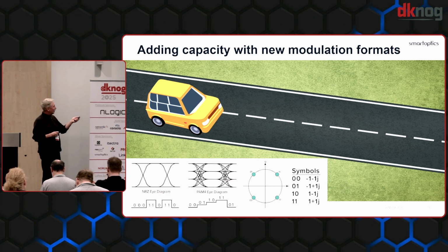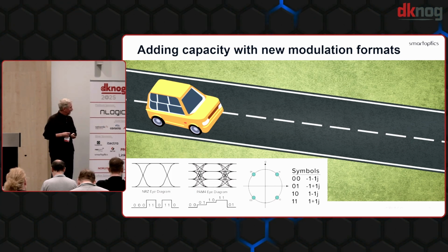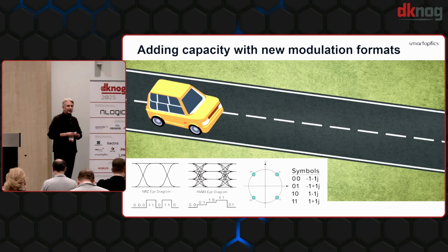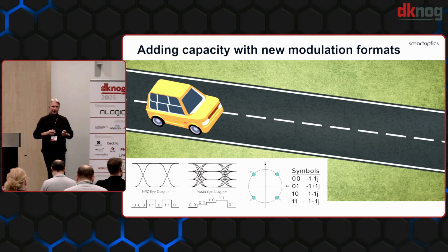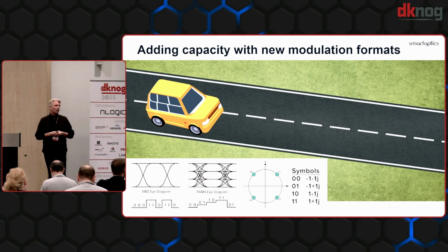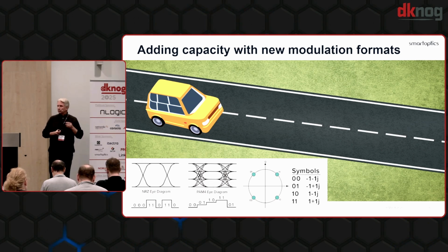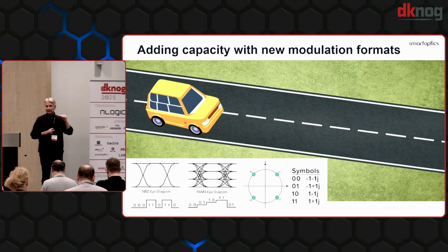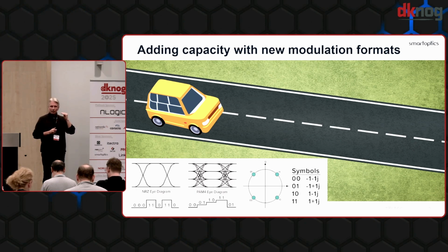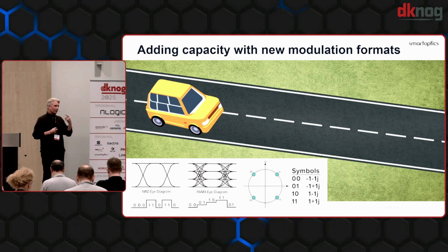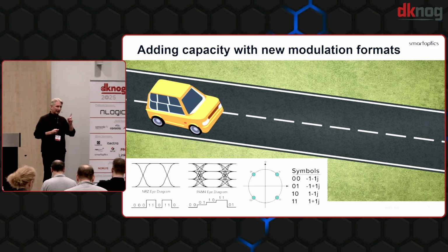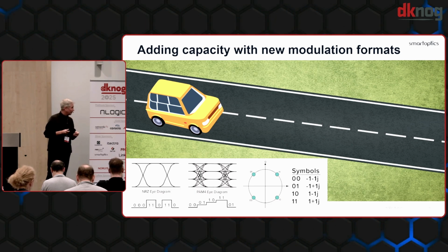If we look at the modulation format, NRZ modulation is a modulation where you have 1 bit representation per clock cycle. Normally people talk about turning the laser off and on. That's not really how you do it. You have different light intensity levels that represent 1 and 0. So the 2 states that you can have are 1 or 0, so it's 1 bit representation that you can have on 1 clock cycle.